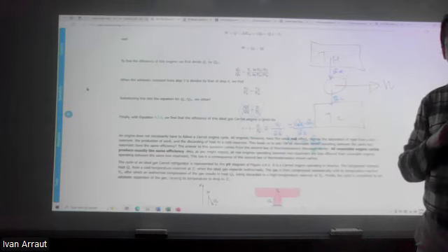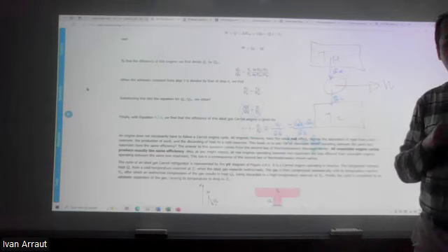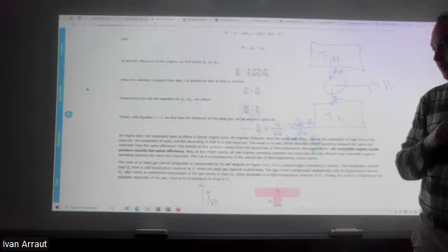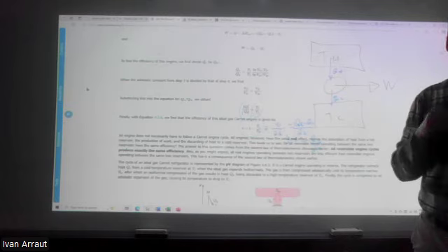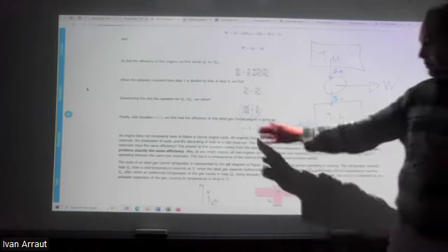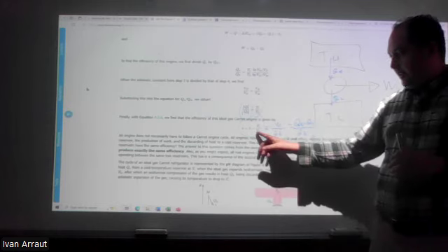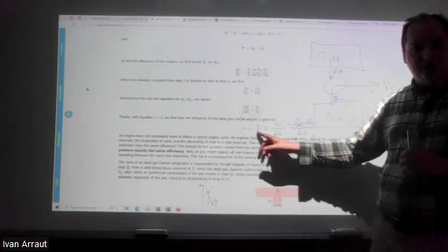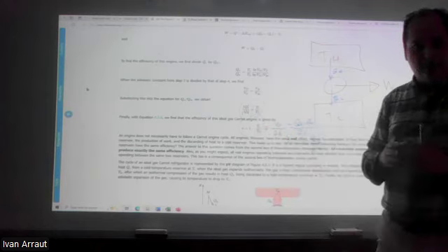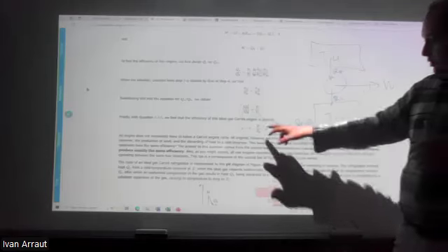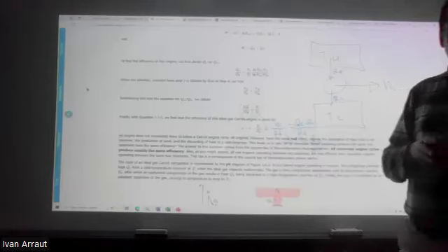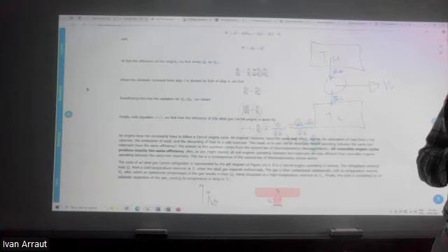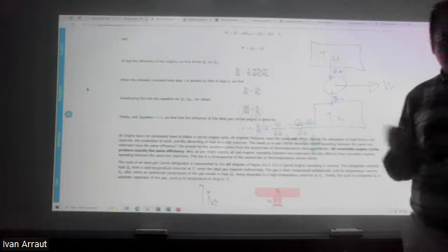The heats divided by the total heat, that relationship is equal to 1. Okay, that's what you mean. Well, looking at these variables, it is equivalent to say the larger the temperature of my source is, the more efficient my engine will be, or the colder the temperature of my sink, the much better in that sense. Because those are the variables I can control.